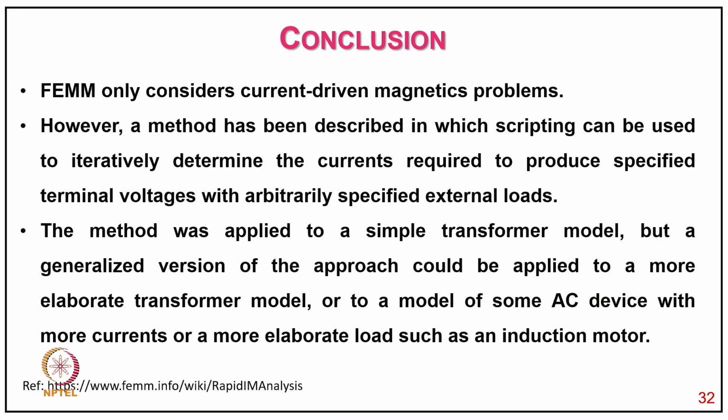Now coming to the conclusion: FEMM only considers the current-driven magnetic problem. However, a method has been described in which the script can be used to iteratively determine the current required to produce a specified terminal voltage with an arbitrary specified external load. The method was applied to a simple transformer model, but a generalized version of the approach could be applied to a more elaborate transformer model, or to a model of some AC device with more currents or a more elaborate load, such as an induction motor.